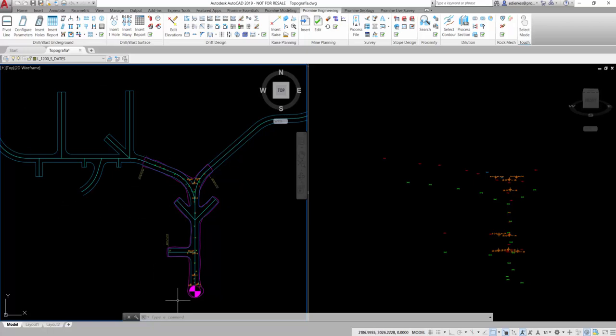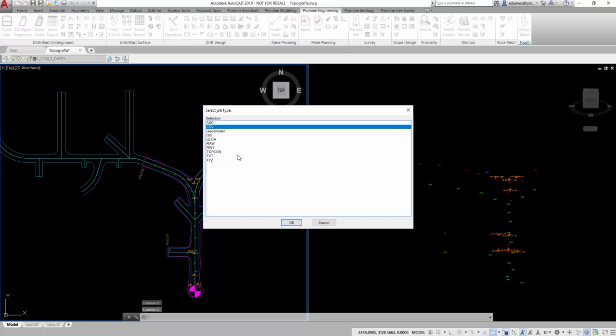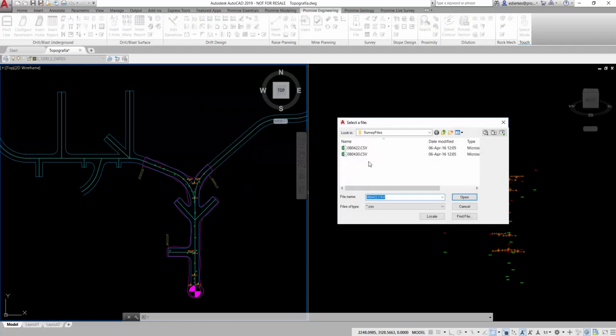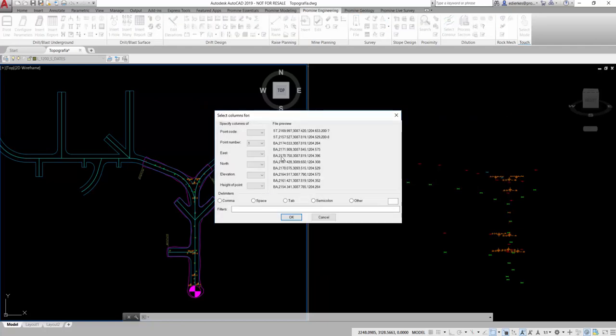information of some segments. As the survey has progressed, we're going to insert additional survey information on the west part of this level by using the Process File command. In the first menu, we can choose between different file types that can be read, like RW5 and TopCon. In this case, we're going to choose the CSV file. We're selecting the correct file, and a new menu will open in which we can sort the information of the file into the correct columns and determine our delimiter.